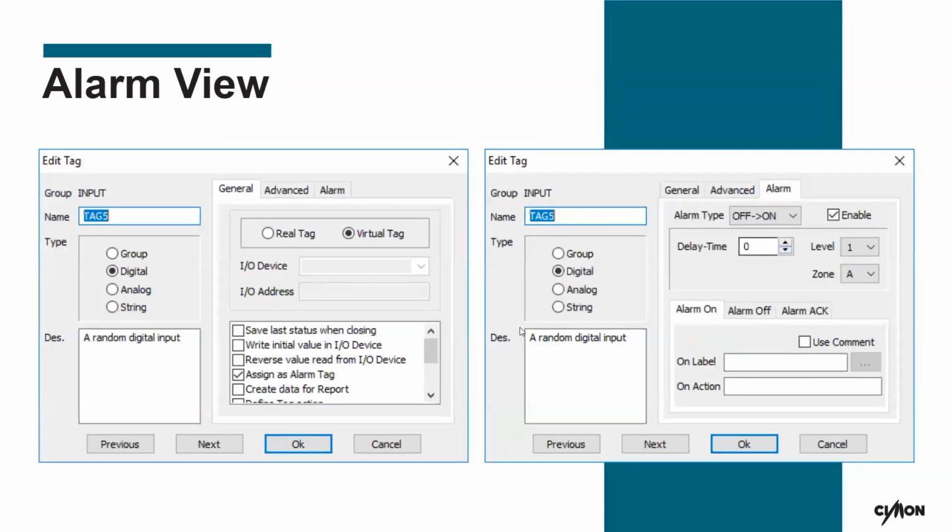All right, so that's how you create alarms. You can also have alarms for Boolean values. So if you have a digital tag, when you create an alarm, you'll have a different interface. You can just choose between off, on, off, of that nature, whether it's off always or whether it's on always. It just depends on your application. So you can have alarms for Boolean tags and analog tags.